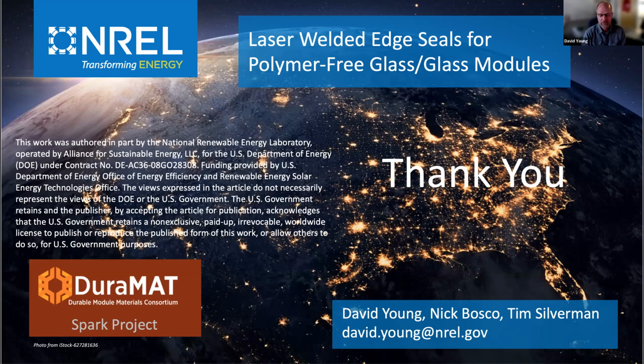The optical matching? That seems like a device to device optical matching problem. So you have to put an ARC coating on the bottom of one and the proper ARC on the top of the other to match there. A lot of people have a question about, if you don't have any polymers, what happens to your optics in the module? So my answer to that is put an ARC on the outer surface and the inner surface of the glass, and that's solved.